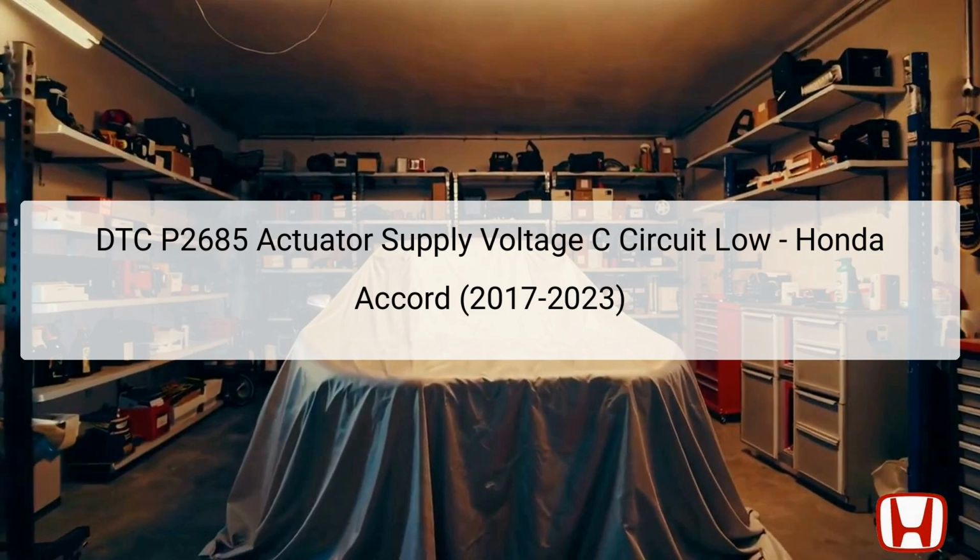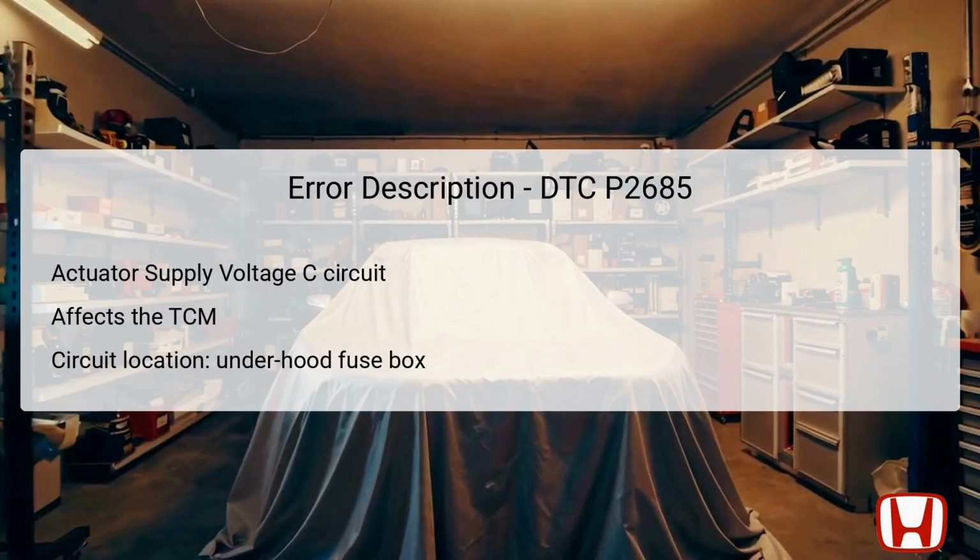between 2017 and 2023. The error code P2685 pertains to the actuator supply voltage C circuit, which provides voltage to various actuators and systems controlled by the Transmission Control Module, TCM. The TCM is a vital electronic component located in the vehicle that manages transmission operations by processing data from various sensors and input sources. The supply voltage should ideally remain within specific parameters for optimal functionality. But when it dips too low, it leads to this particular DTC error.